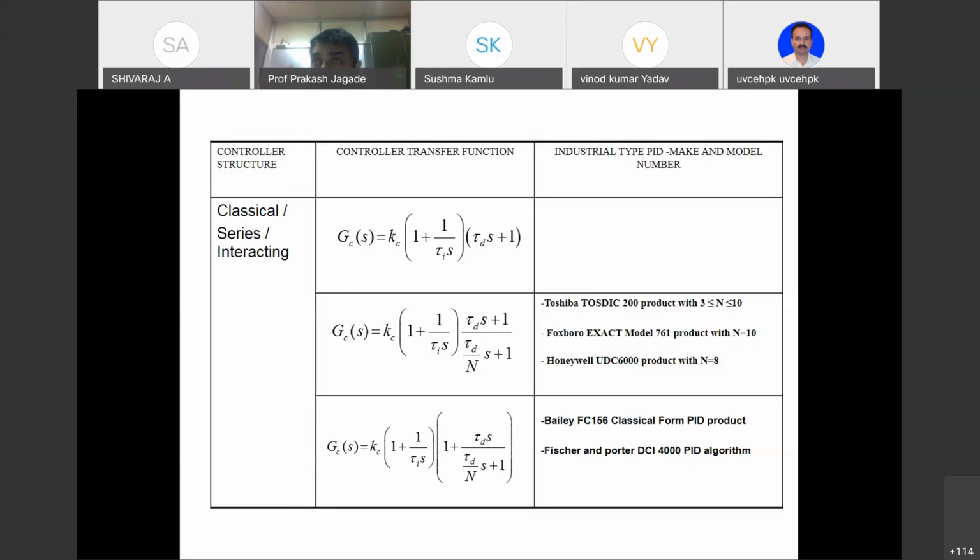But this transfer function has to be converted into an algorithm, which one can easily do. Convert this into a difference equation. Once you are able to convert this into a difference equation, then you can write a recurrence relationship. So you can easily convert this transfer function into an algorithm. You simply do numerical integration, numerical differentiation, and amplification. Thereby you can achieve proportional, integral and derivative action.